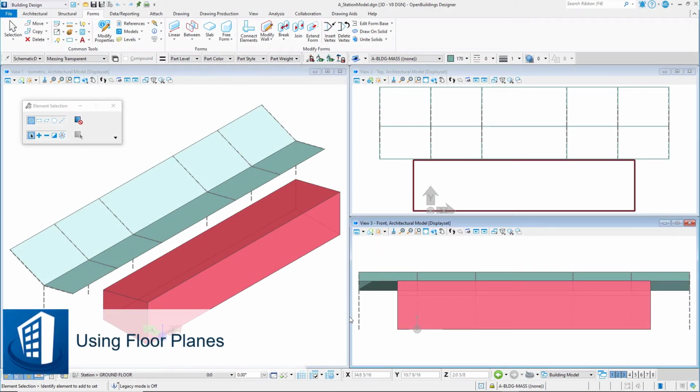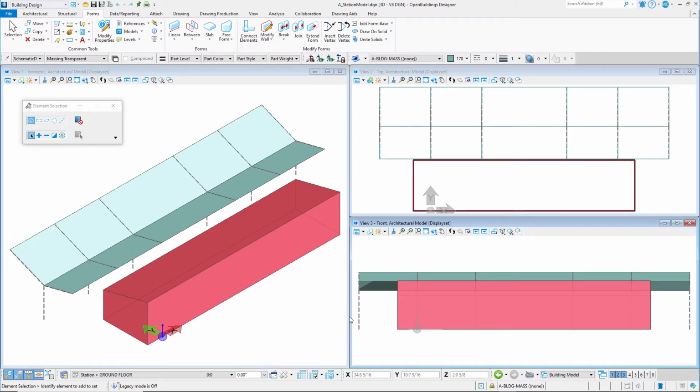Floors and reference planes are used to help you model elements at the correct height in the 3D model. In this exercise, you will create a floor reference in the Floor Manager, then select the new plane from the Floor Selector to set the working plane and the appropriate snap blocks.